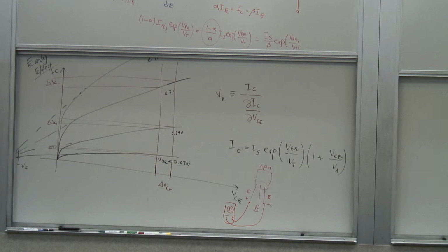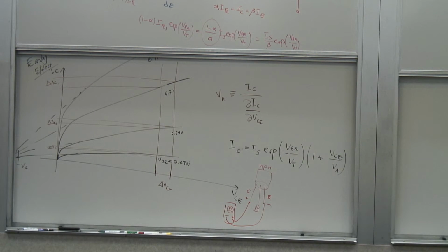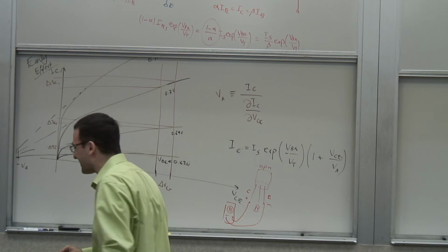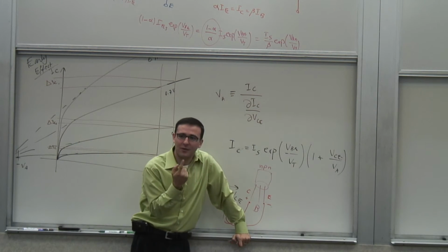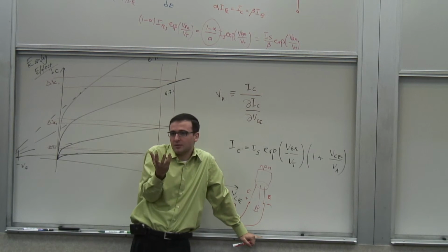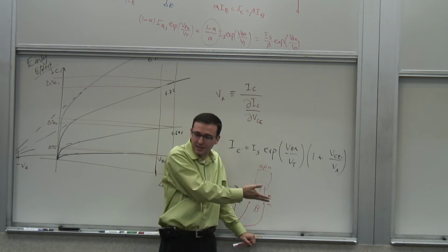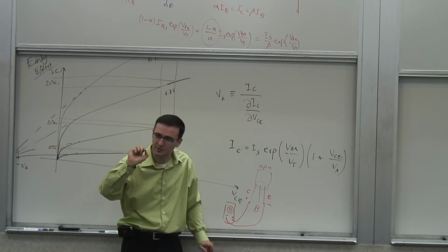But why? What's happening? Are you warming the... No, it has nothing to do with that. Just touch the tip of the terminal. Just touch it. You will see. We have some potential. Well, I have a lot of it, but so do you guys. But I also have charge in addition to it. My body has some electric charge, and when I touch this, I'm not necessarily at the same potential as this. So there will be some injection of charge into this thing. A little bit of charge, basically there's a little bit of base current.